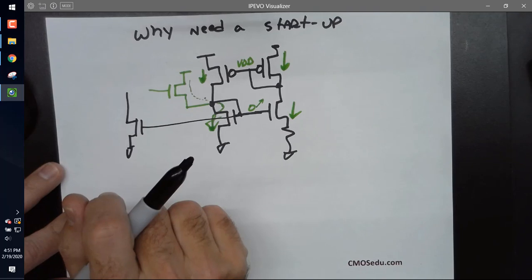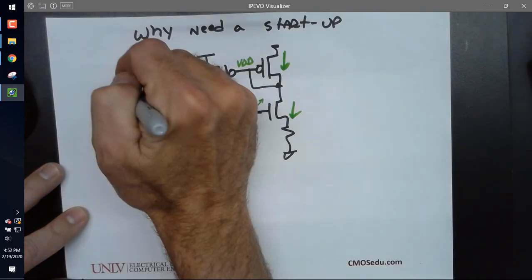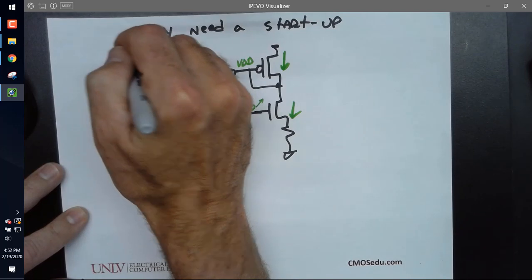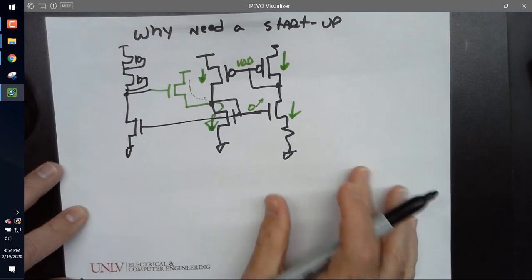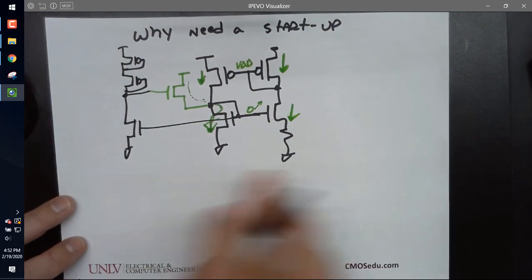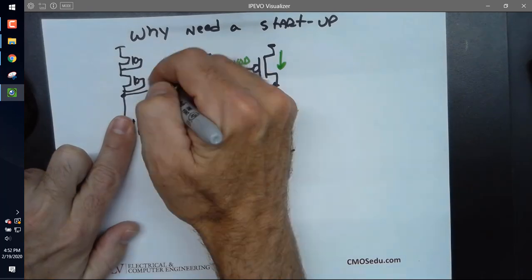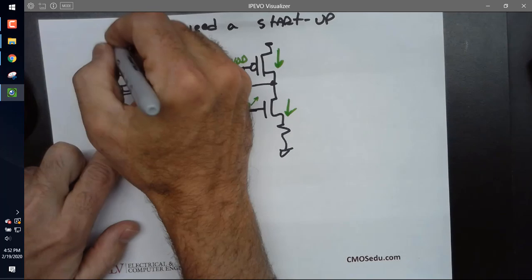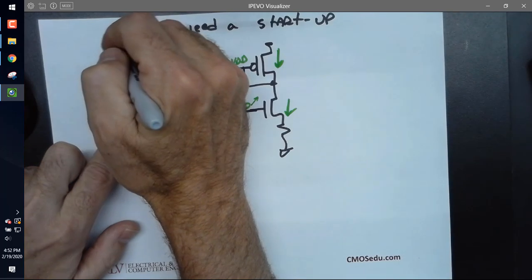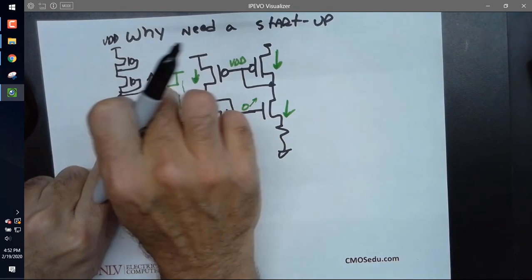Zero. So what I'm going to do is connect it right here and put a couple of transistors here. You have to design it and characterize it. If this is zero, these are gate-drain connected. What do these transistors pull this node up to? They pull it up to the power, VDD. There's no place for the current to flow, so they will leak this node up to VDD.